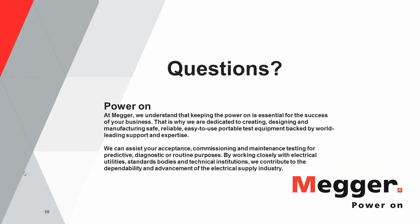Okay, next question. Is primary injection testing a destructive test? Okay, so the question is kind of valid, that when you're trying to run the test, you are injecting a huge amount of current through the breaker. But if you think about it, and if you look at the breaker time-current curves, the breaker is supposed to handle those kind of current for a short period of time.